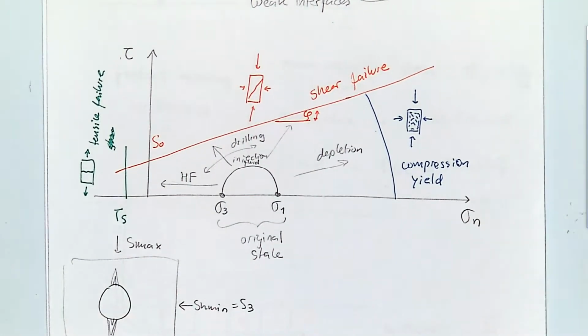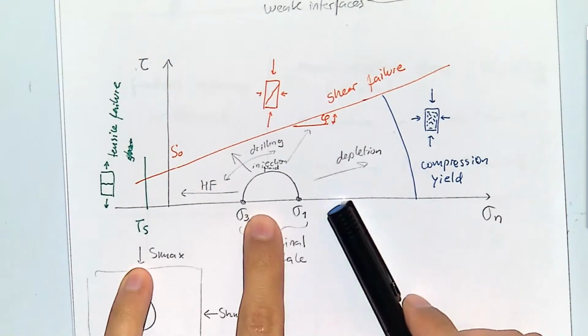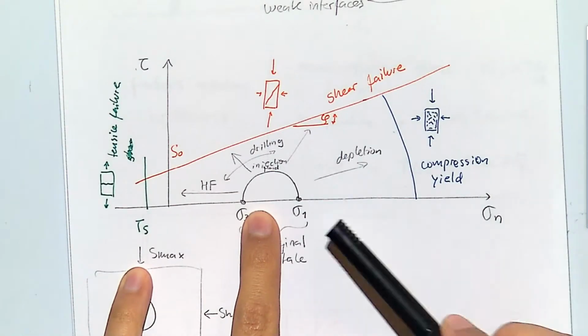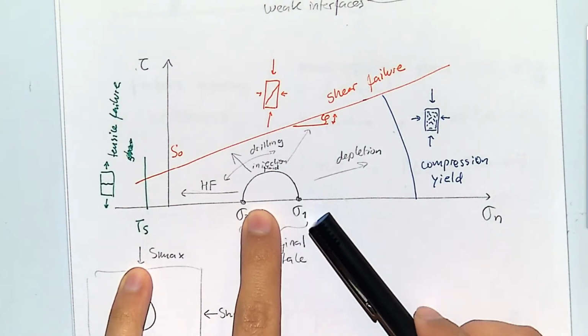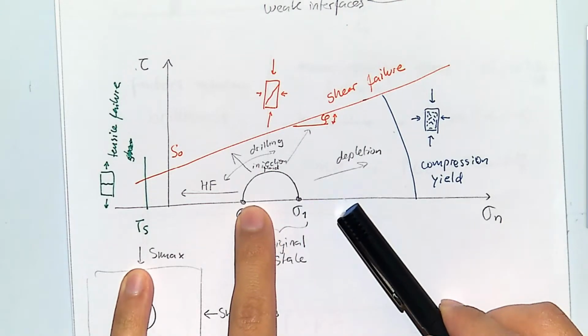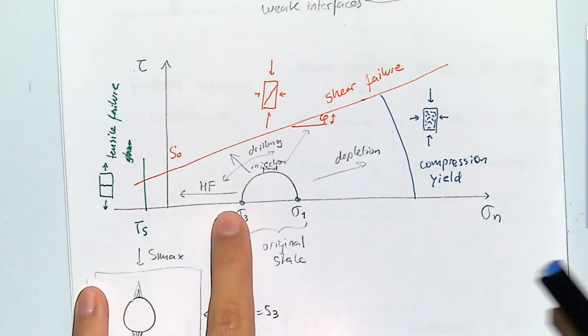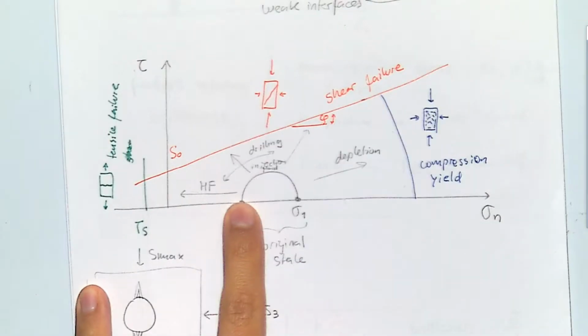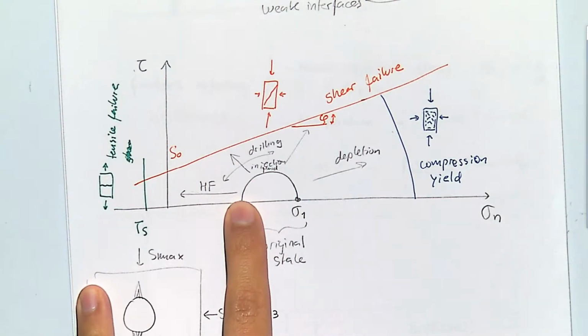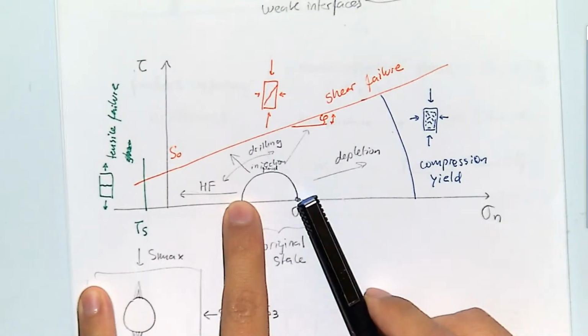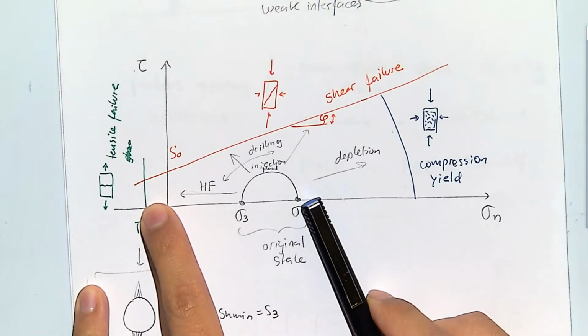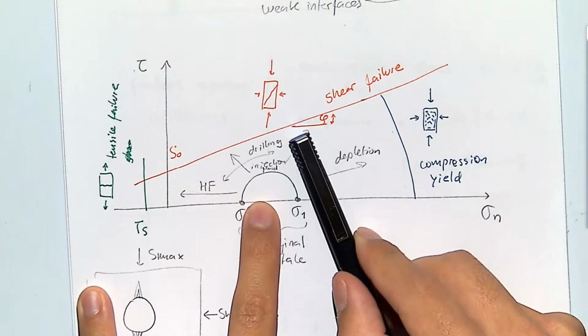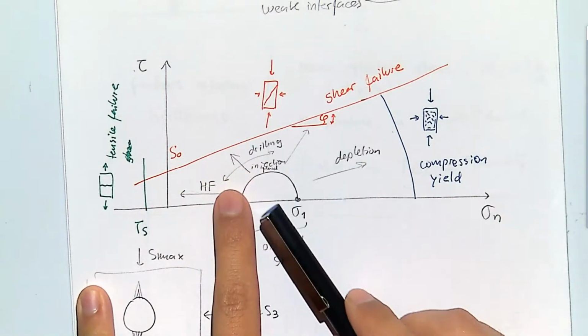And after that, we put together something very important. Here we discuss that for a given in situ state of stress, the rock may be happy, maybe not at failure, but then we can cause different actions, we or nature, in which we can get the rock to tensile failure to the left, to shear failure to the top or to the right or in this direction.